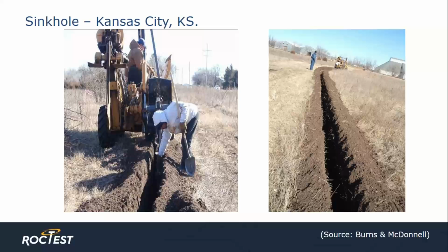After burial, the soil was mechanically compacted to create a solid bond to the cable, allowing for efficient strain transfer. Installation of the cable was done with traditional trenching. However, due to the site's rural location, the installer discovered that the prairie dogs had chewed on and damaged several locations of the cable run. A new, more robust cable needed to be reinstalled with a more rodent-proof outer jacket. From that lesson, we developed the current Hydro&Geo cable that also has an armored version.